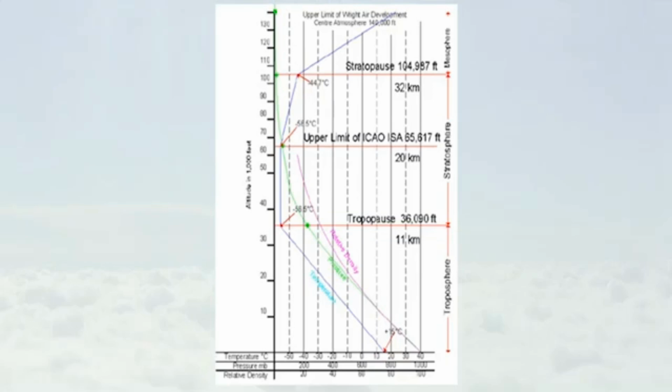Having made these assumptions, the pressure corresponding to any given level in the ISA can be calculated from the calibration formula. Graphs or tables can be produced showing height in terms of pressure under standard conditions. These tables can be used for the manufacturer's calibration of the altimeter scale.